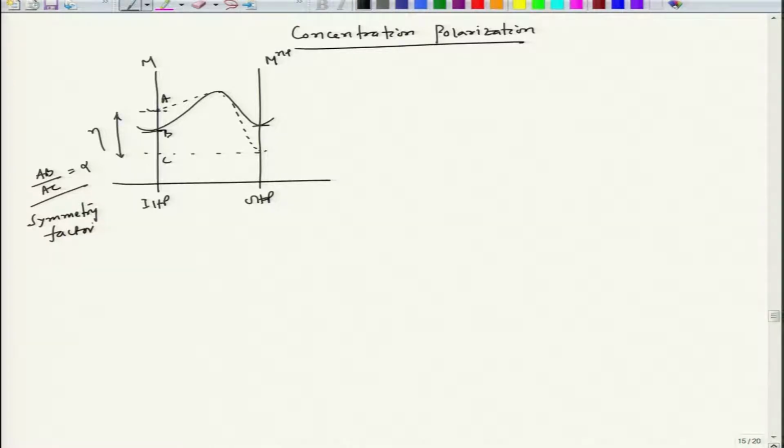In this particular case, IA is greater than IC for the dotted line, and this is the corresponding situation for I0, where IC equals IA. Now, it is basically a thermally activated jump process, and it happens at a smaller current density level, and the basic assumption is that when this happens the concentration at this particular end does not change.